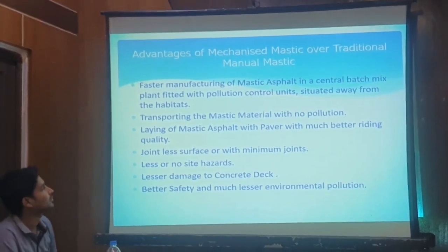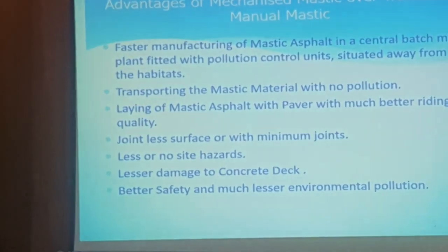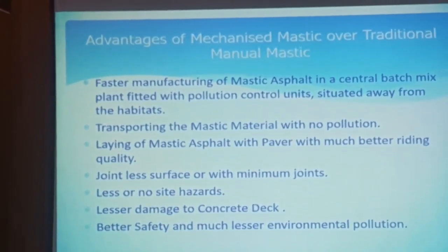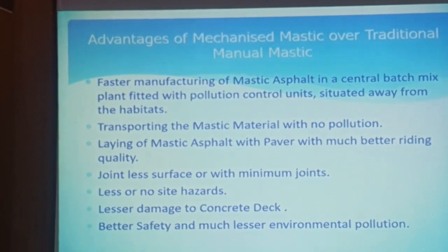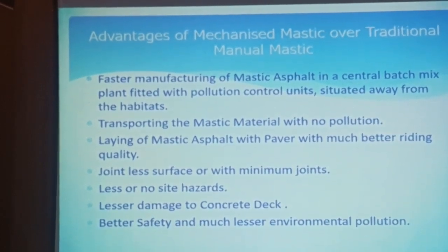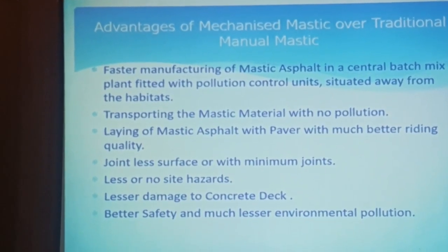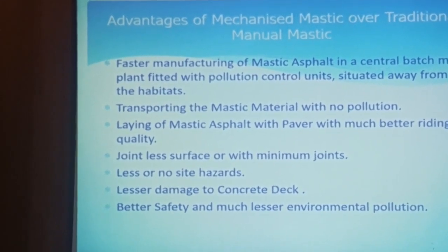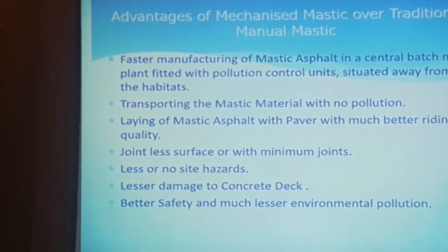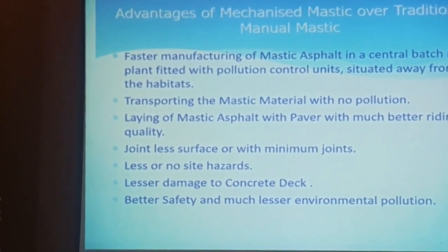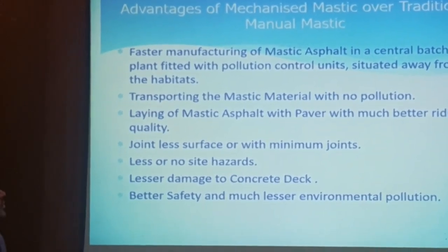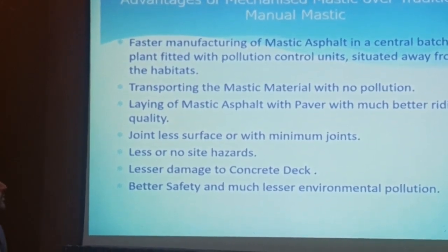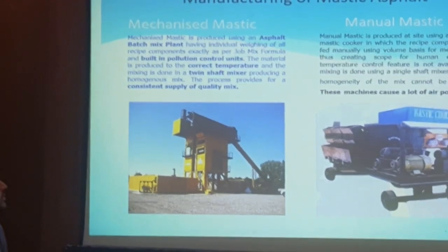These are the advantages of the mechanized mastic asphalt. Faster manufacturing of the mastic asphalt in a central batch mix plant, transporting of the mastic material with no pollution, and laying mastic asphalt with a paver. With a paver we lay, so my riding quality is much better. Jointless surface with the minimum joints, less or no site hazard, lesser damage to the concrete deck, better safety and much less environmental pollution. Okay, so there's a difference.